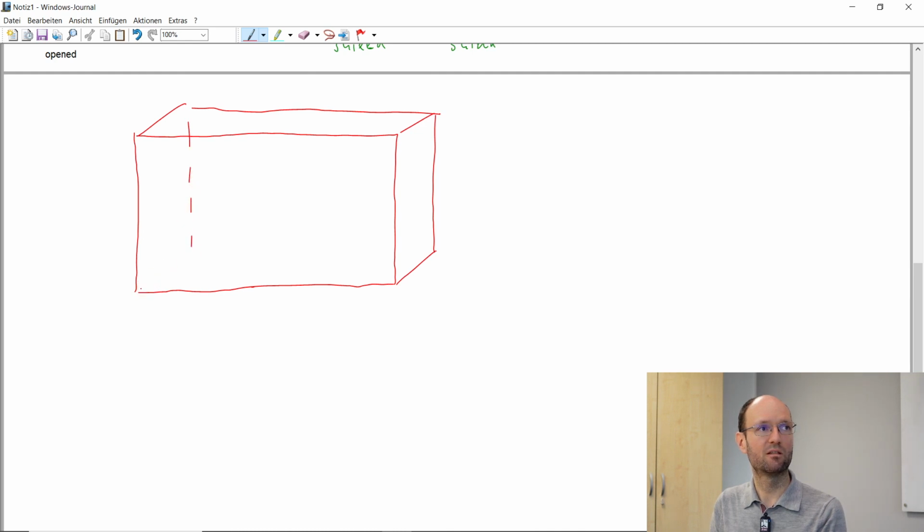So this is all made out of steel, and then we might have some apertures, some openings somewhere where field can couple in. So for example, we have some slot here on the front side for some display or whatnot, and some field can couple in here. And on the outside would be our field generating antenna, and this now creates some field, and this field will couple into this enclosure.